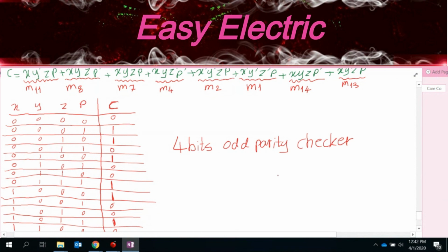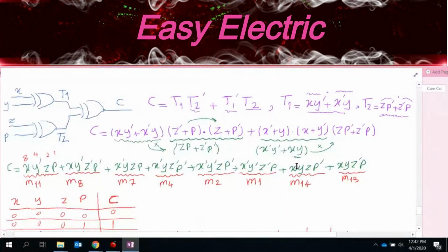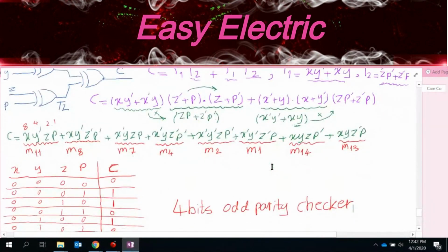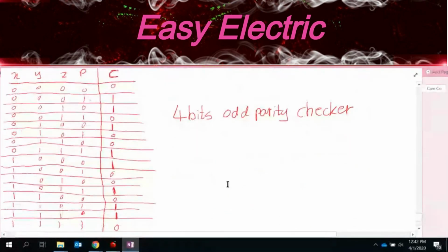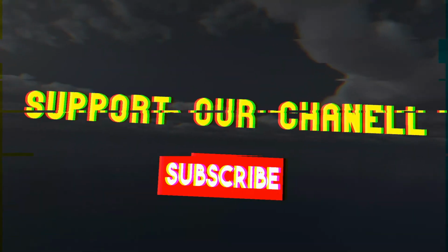Okay. So this is how you could analyze a combinational circuit, okay. So again, you just find the Boolean function of the output based on your real inputs, which here are XYZ, get the standard form. Then draw the truth table based on that function, and take a look at the truth table and look for a basic function or any other function inside it. Okay.